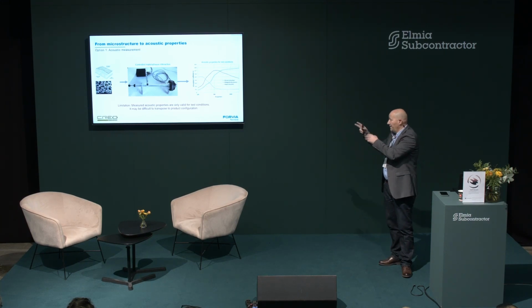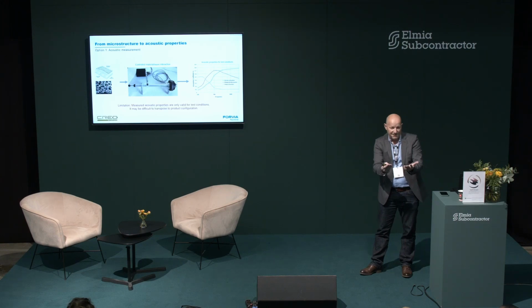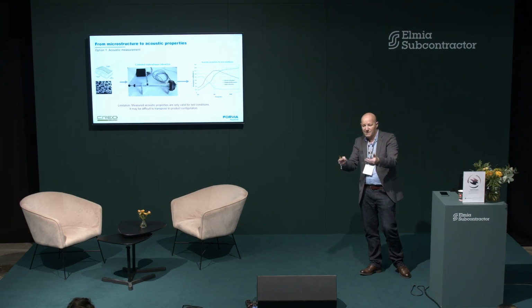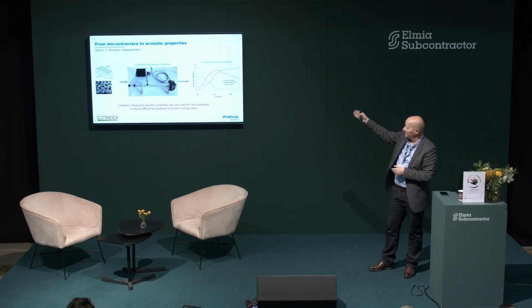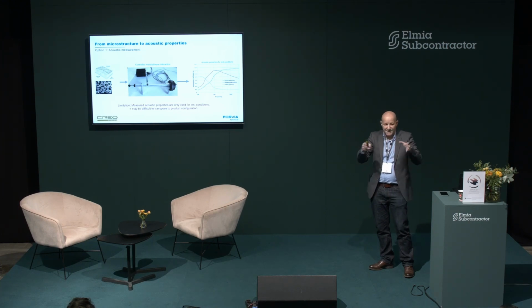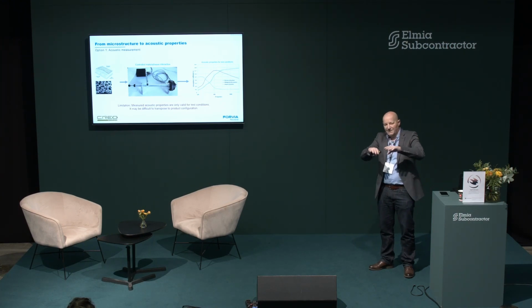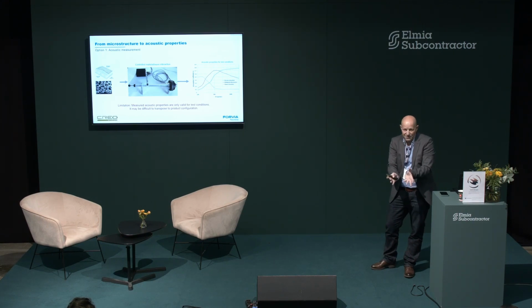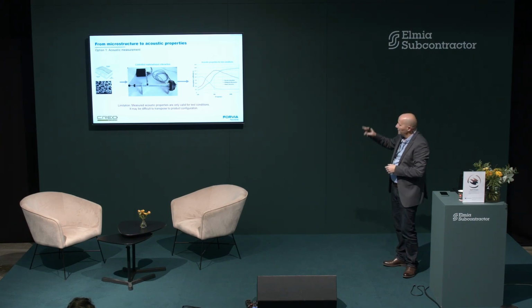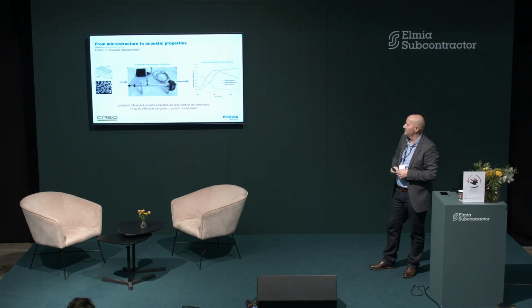This information is also usually the information you get when you buy a material and you want the acoustic specification on the material; you will get a curve like that. What is very important to understand is that this specification is valid in this simple configuration. When you are going to take your material and put it around your source in your design, you very seldom can exactly use this quantitative data.